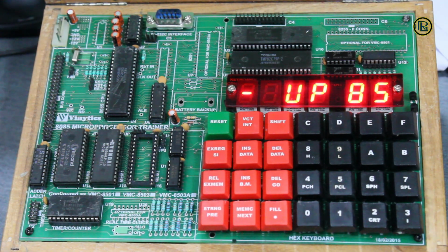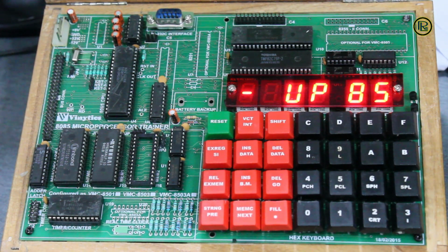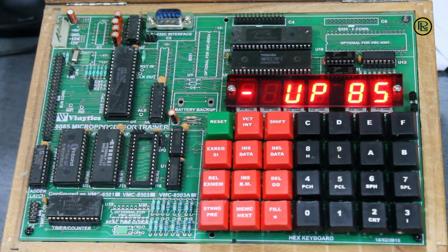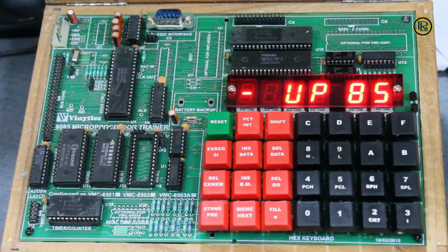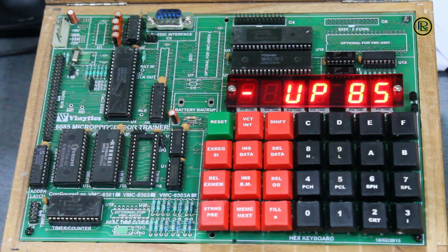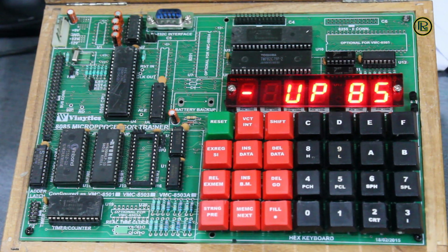Now we will be writing the program for the second problem, that was subtraction of two hexadecimal numbers using direct addressing mode. So we will be using the same numbers. The numbers are 8F and 3A. As 8F is bigger than 3A, I have to subtract the smaller number from the bigger number. So the program here is written accordingly, such that the bigger number comes above and the smaller number comes below.